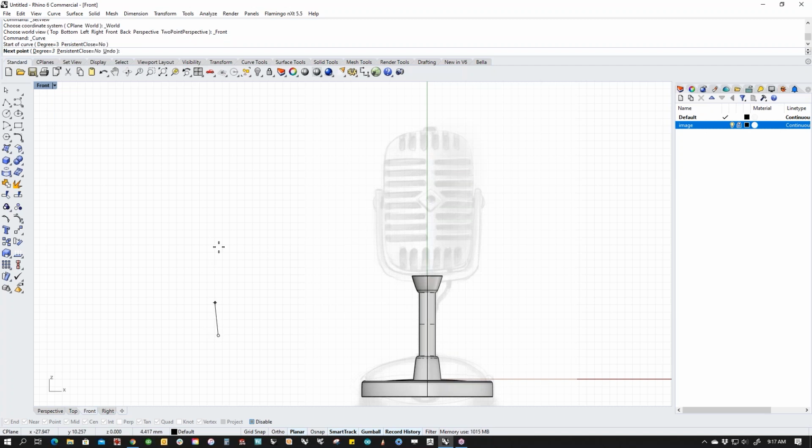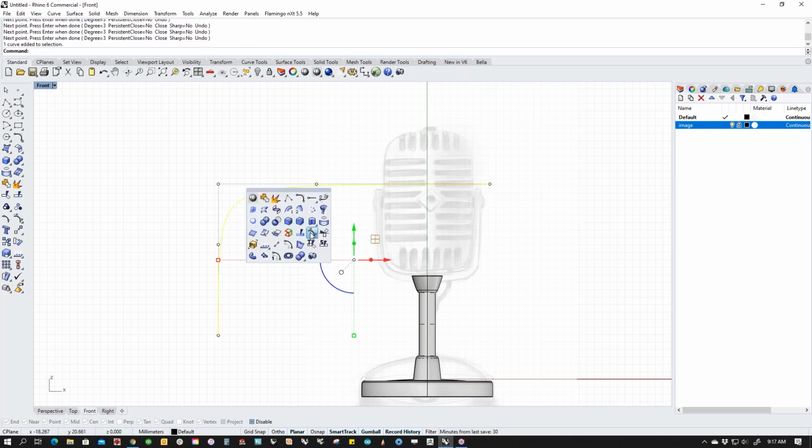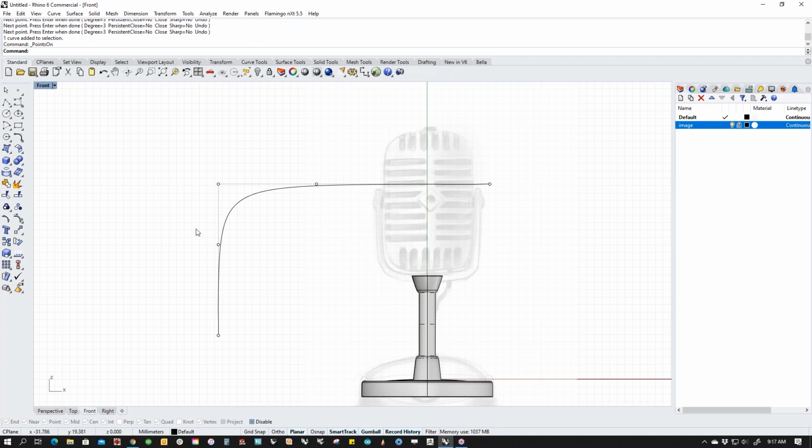So I've got a point that's leading into my corner, right? This is my anchor point. This is the first point of my corner, the second point of my corner, the third point of my corner, and then there's a lead out here, right? So if I were to evaluate how this corner is set up, if I need this to be tighter, I just move the 3 points closer. If I need this to be softer, I just move the 3 points apart.